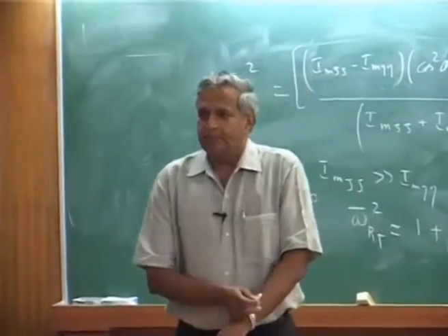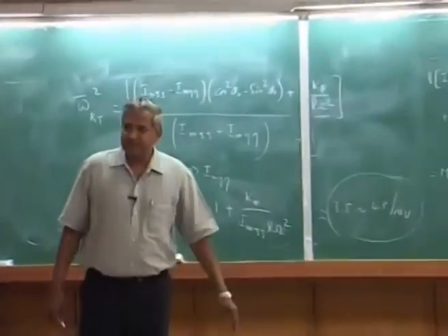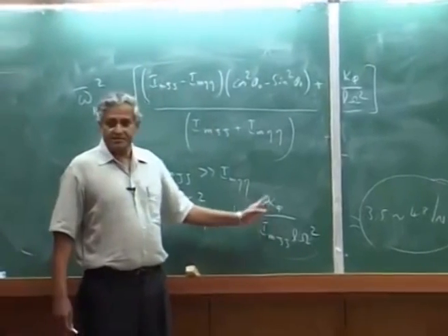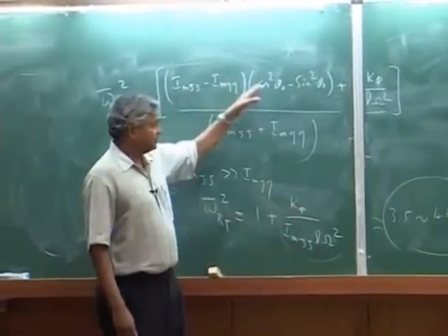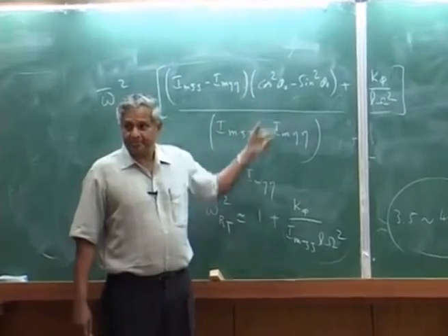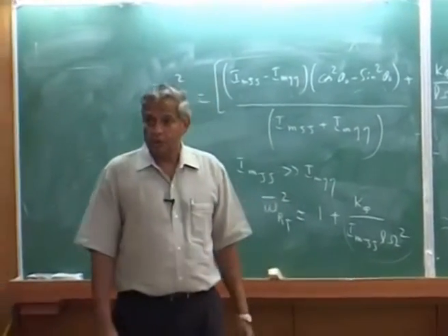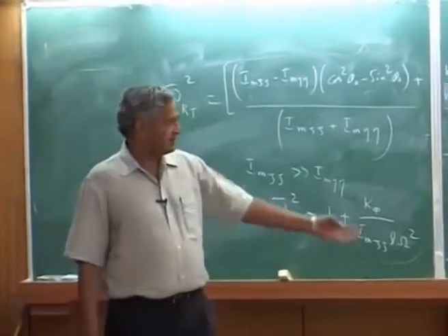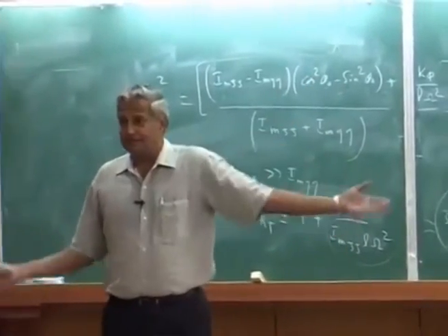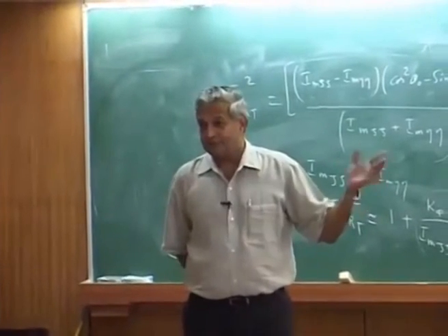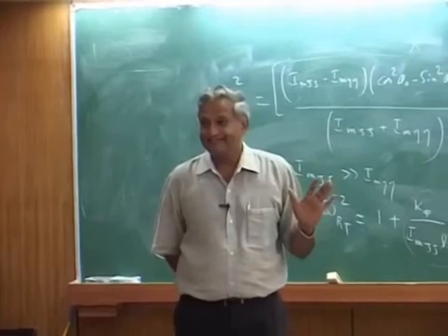That's all. So fixed wing and rotary wing, other than, say, the axial force which is acting, what would be this thing while calculating? Torsion is pretty much, there is no rotation. That's all. This is free. Fixed wing is only this. There is no rotation. This will not be there. So but like modeling, say, a rotating blade and a fixed blade. Fixed blade is simple. Just a bending torsion problem. What you have learnt in structures 1 course. That's all.